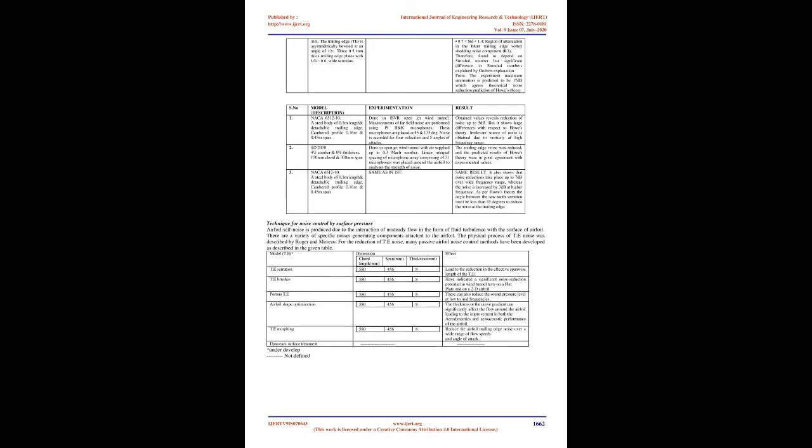Most important, up to 7 dB turbulent boundary layer trailing edge broadband noise reduction can simultaneously be achieved without compromising the aerodynamic performances in lift and drag. The Poroserrated trailing edges do not cause any noise increase throughout the frequency range investigated here. The reduction of the turbulent broadband noise is primarily caused by the serration effect, but under a condition that the sawtooth surface must be solid and non-porous.